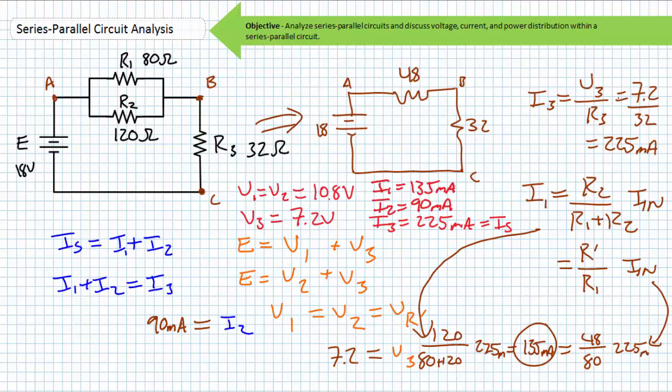All desired voltage and current values have been solved for, and at no time was it absolutely necessary to solve for total resistance, reduce and return, assume a value and backtrack, or perform a complicated ladder network analysis. All circuit properties are immediately accessible via skills you should already feel comfortable applying with little outside guidance. Ohm's law, the power equations, current through elements in the same path is the same, voltage across paths in parallel is the same, what goes up must come down, what goes in must come out.